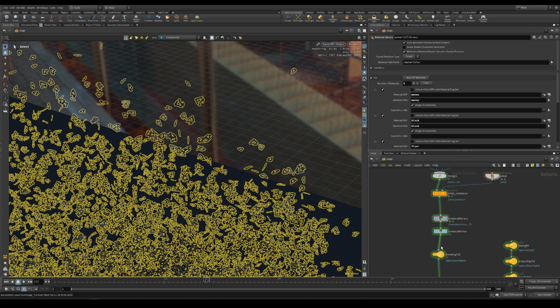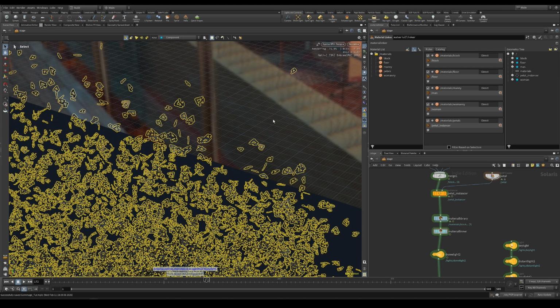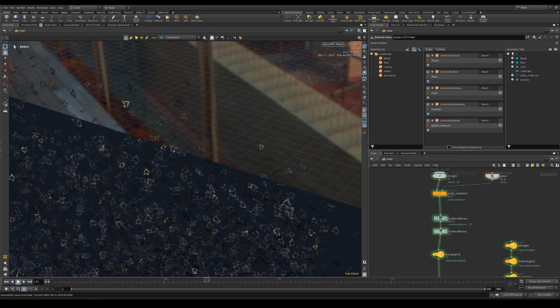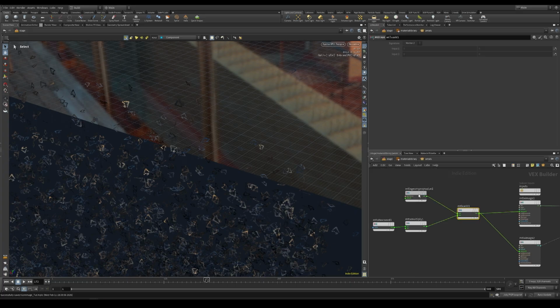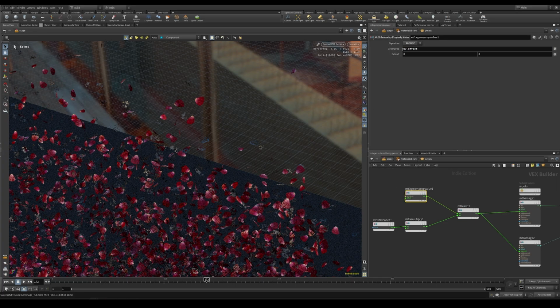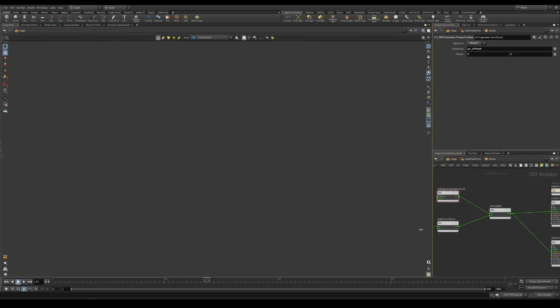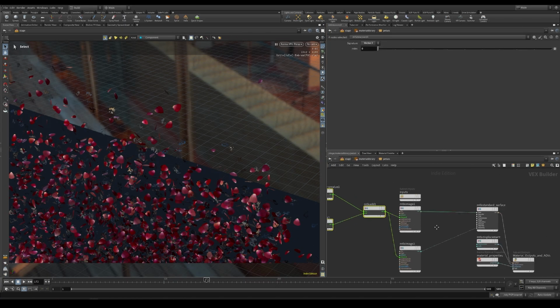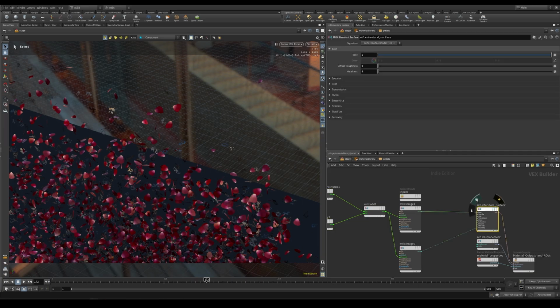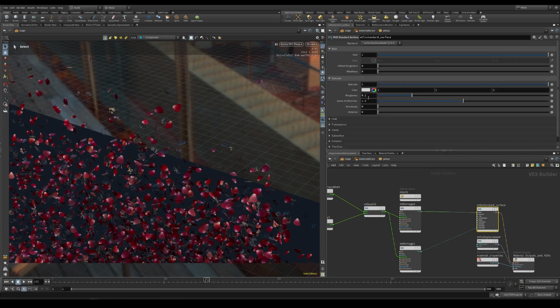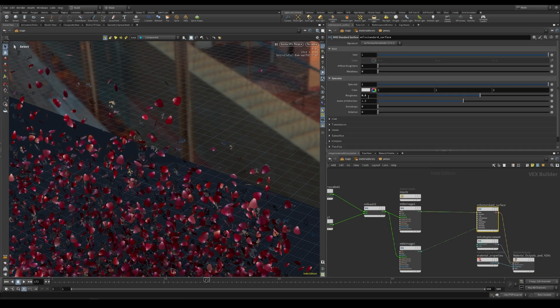And we don't. Why we don't? And why do I see all this outline? Because we didn't call offset, we called UV offset. Yeah, now it's working. And finally, for the petals, I want to set the specular, or rather the roughness to, let's say, 0.6. And let me restart the render.